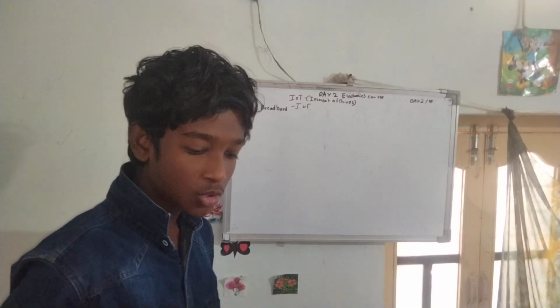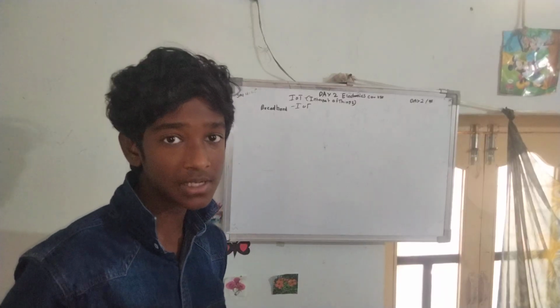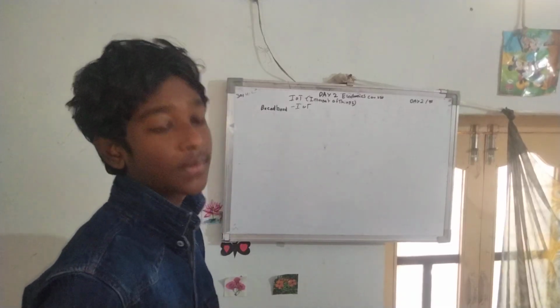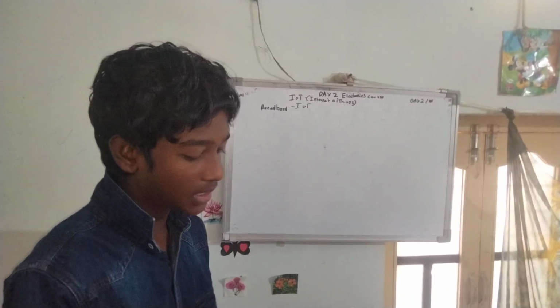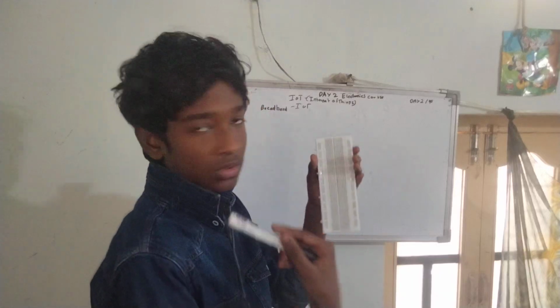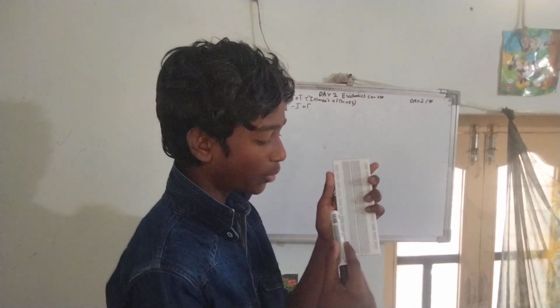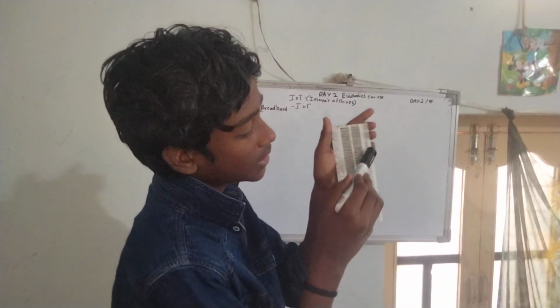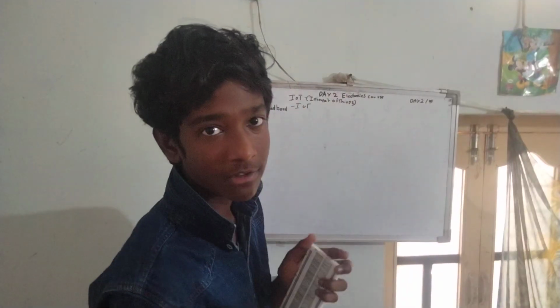So through one battery, we can connect multiple devices or modules. This is very useful in organizing things and connecting each other. This is the work of power rails. We find these power rails on the two opposite sides of the breadboard, left side and right side. It's all interconnected like this, so the power is distributed equally.